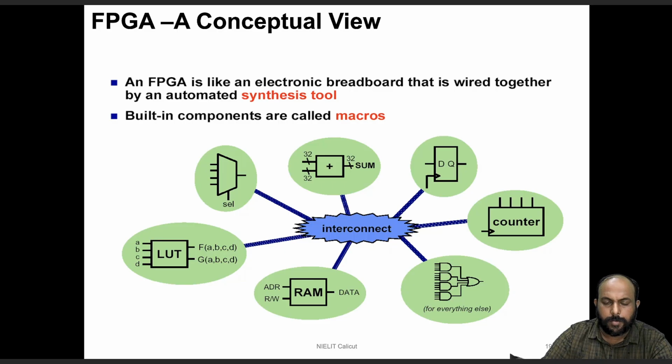So FPGA can be imagined, though this is not an FPGA as I told, intuitively as a reconfigurable platform wherein all these elements can be made to be incorporated in the design as intellectual property codes, and connections can be established in a reconfigurable manner. These built-in components, you often call a macro, and the wiring part, the synthesis part, or the building part is done with the help of certain electronic design automation tools. Most of these tools are called synthesis tools, which take the RTL as an input and convert it into the equivalent structure.